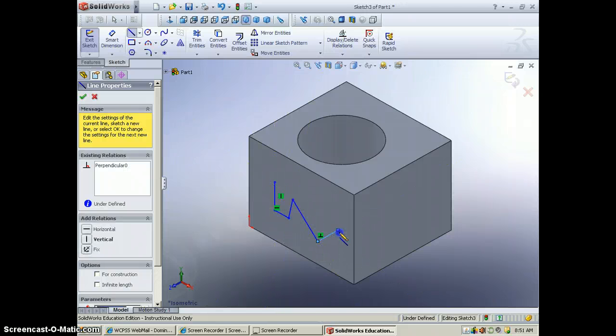When you draw lines, they all need to be connected, and in the end, it has to be completely closed. So I cannot leave my drawing like this and then do something with it. I must close this off like that, and all those lines must be touching each other. Now I just drew that with this facing out at a slant.